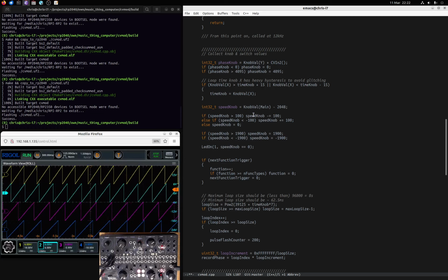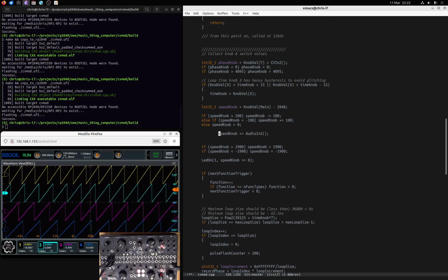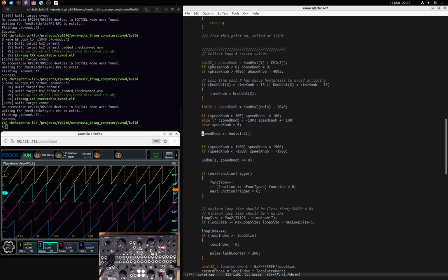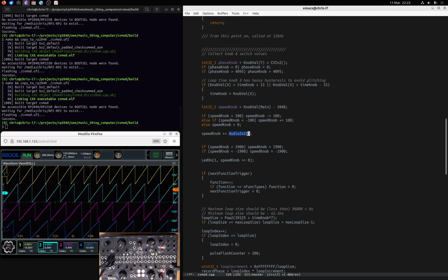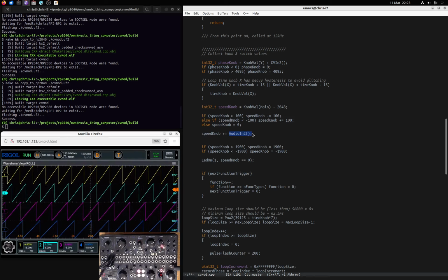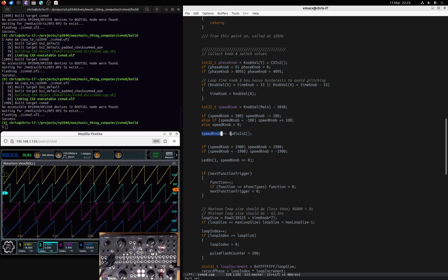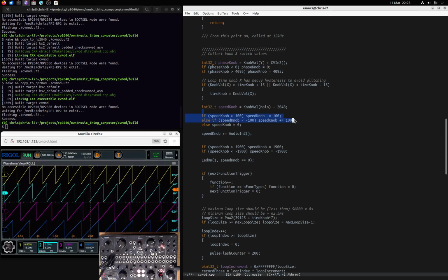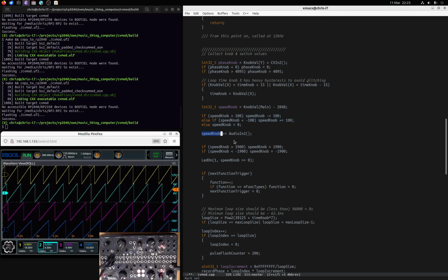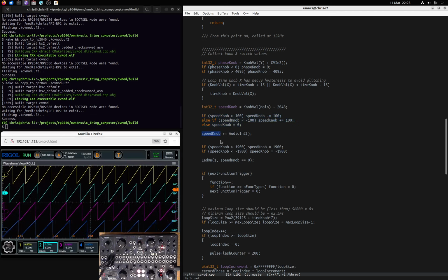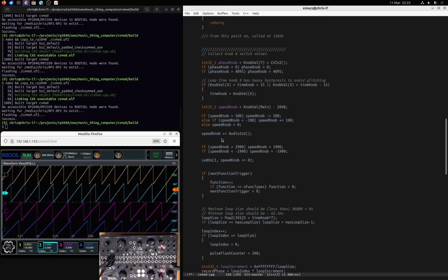exclude it, because with the normalization on, we're using the normalization probe. That means that when there is no jack plugged in, audio in 2 will produce exactly 0. So by adding that signal on after we've produced this dead zone effect on the speed knob, that's not going to cause slight creep in the speed if we haven't got a signal patched in.